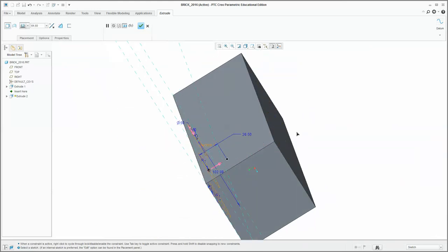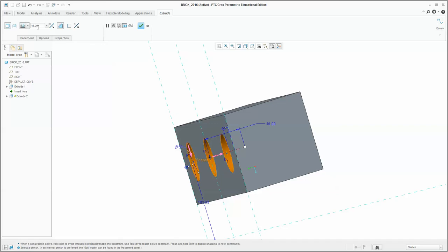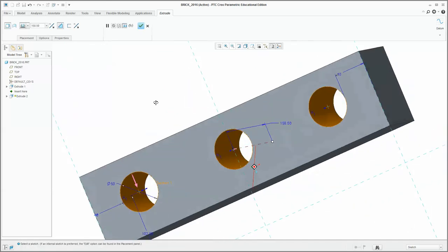If I bring it back, I can click on this white thing. I can extrude out, I can extrude through. Once you extrude through and remove material, it's got no relevance. There's nothing there. You could also go part way through if you wanted to create a bit of a cavity. You can do a few things, or of course you can come back and say that's 100. Now I'm going to go all the way through for this particular exercise.